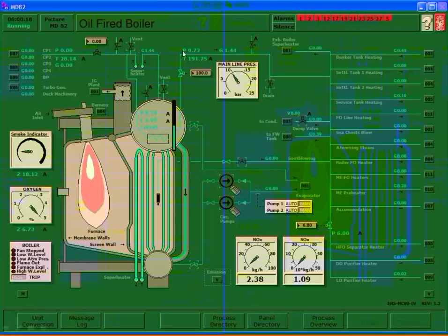The reason why you don't use superheated steam for saturated services is that it is at a high disadvantage. Go look into your tables and look up the coefficient of heat transfer of superheated steam. It dramatically drops. And it's a very simplistic answer for that. With superheated steam, the water molecules are moving at an accelerated rate. They are not in contact with the container for as long as saturated steam, and they tend not to transfer heat.